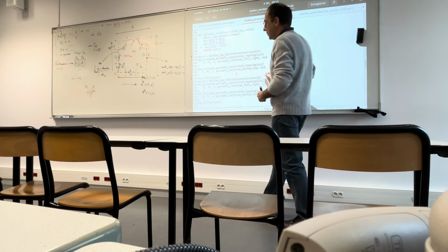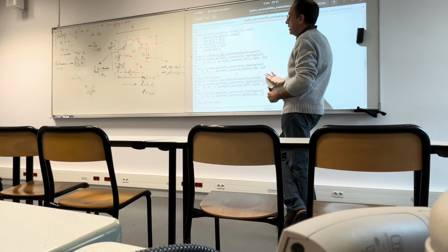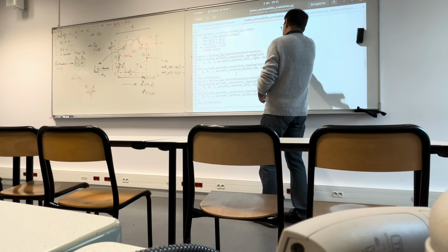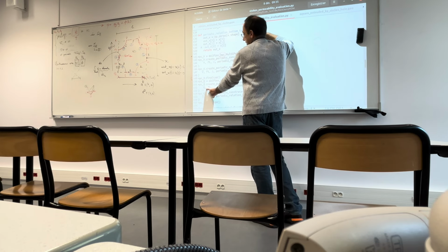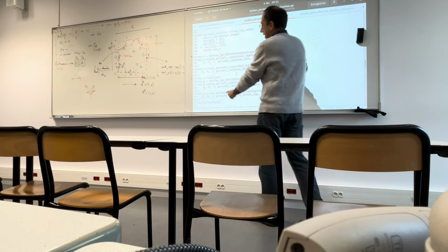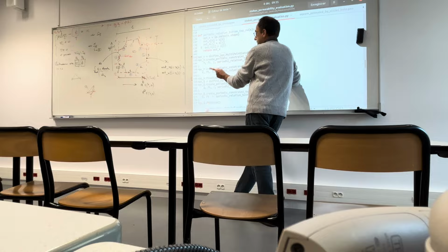And in the same way, exactly the same way, you do it for the pressure. So you have just to switch from the V space, the space for the velocity, into the Q space, the space for the pressure, but the conditions are the same. So we require periodicity for velocity and for pressure.